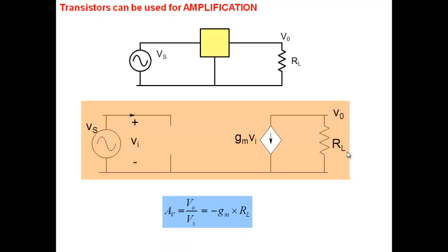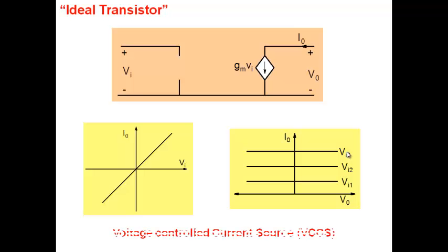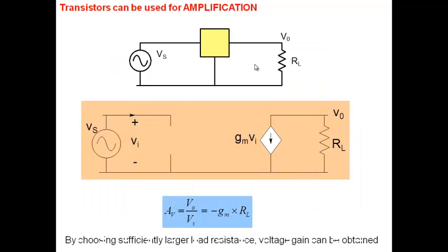All right. So with that background, let's discuss the bipolar transistor. So please keep that in mind. What are we looking for in a bipolar transistor? If you want to understand why that particular structure that I show you is called a transistor, you should be looking for characteristics like this. Is I naught independent of V naught, or very less sensitive to V naught? Is I naught sensitive to the input voltage here? So you should be looking for an element which is something like a voltage control current source. That's what should be in your mind while we discuss a bipolar transistor.